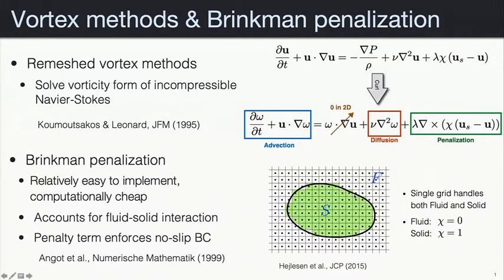We lose the smooth boundary. So usually in the interface cells we smear out the interface, so chi goes very smoothly from 1 to 0, with some intermediate value, let's say 0.5 or 0.3 in these cells. And that's the only special treatment you need.